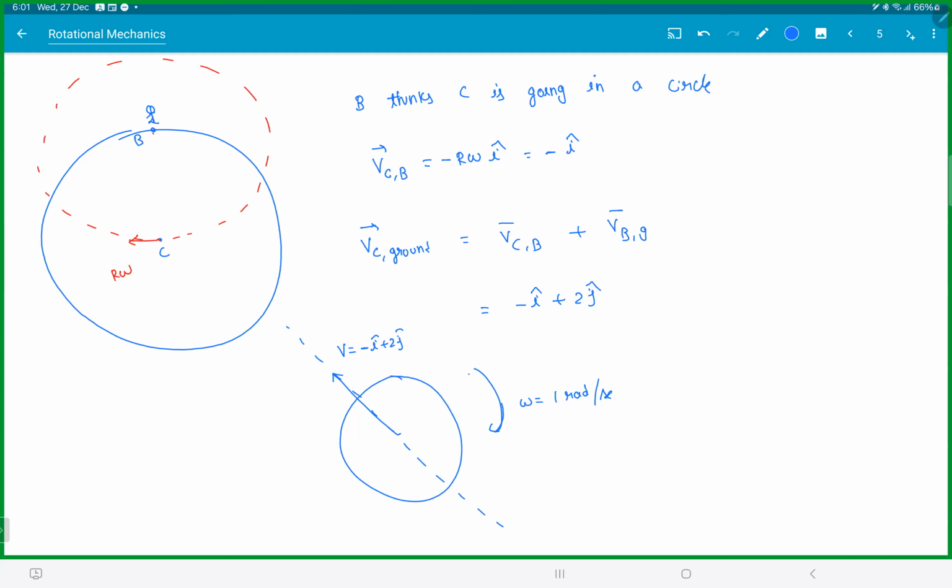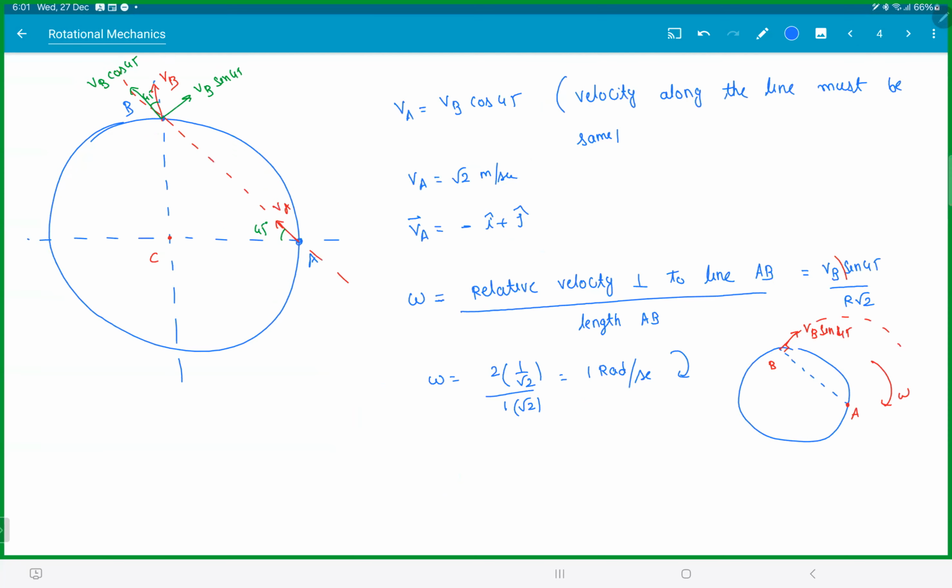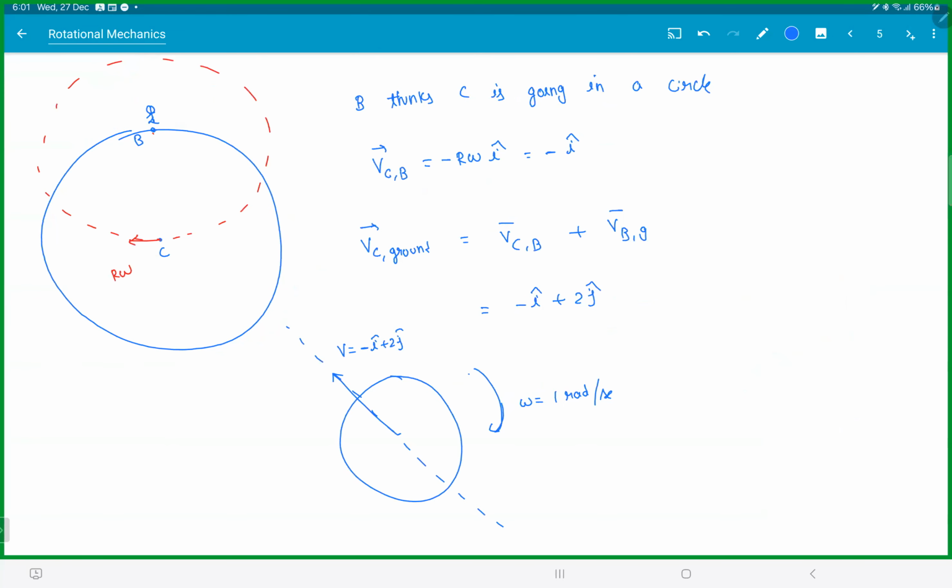Clear, everyone? If you stand on one point whose velocity you already know, it becomes easy from that point of perspective. Let's see one more like this. Any doubts on this, please ask me. So I used the rigid body constraint, then I used circular motion omega relative between two particles, and then we used angular velocity of a body.